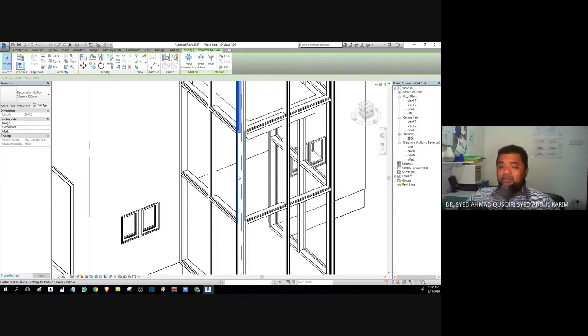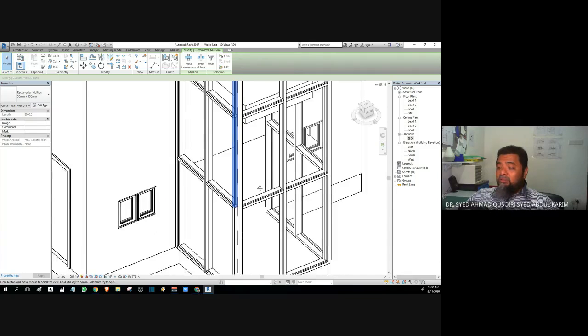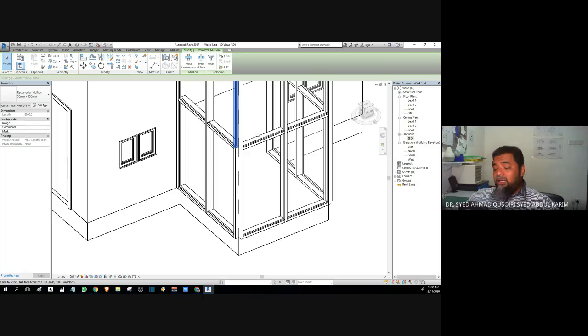If you can get it like this, it's good. You don't need to use the tab key. But if you can't, just mouse over approximately and then press. You don't have to press the mouse, just mouse over and then press the tab. In my case, I press it once, twice, so it's already highlighting that particular mullion. Then I press Control without letting go, and then press the mouse. That's the third one. Repeat that for all the 8 corner mullions and one more set at the other corner. So that's 16.